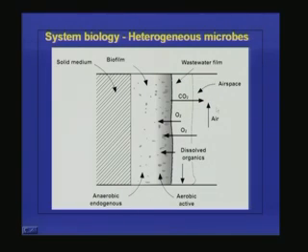So what is happening? Whatever dissolved oxygen is present in the wastewater is entering into the biofilm. You can see that this is the oxygen penetration. Oxygen penetration can take place both from the wastewater film as well as from the air. Air first enters the wastewater, then from this film it enters into the biofilm, and some dissolved organics, as they pass, also enter into the biofilm.